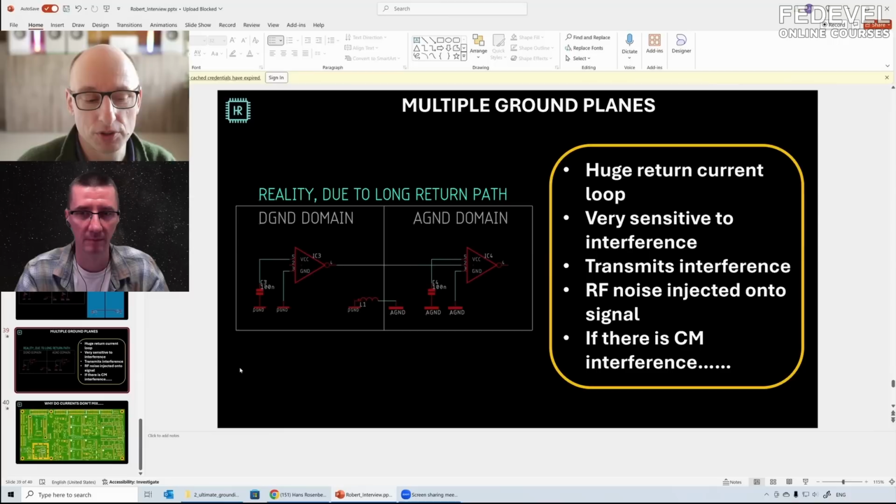Yeah. So the general thing should always be make a single ground plane. But the reason why I try to explain all the underlying theory is that you can think for yourself. And if you have an output power amplifier that runs 10 amps through the ground and you have an input, then you should think, okay, wait a second, I may get some voltage drop.